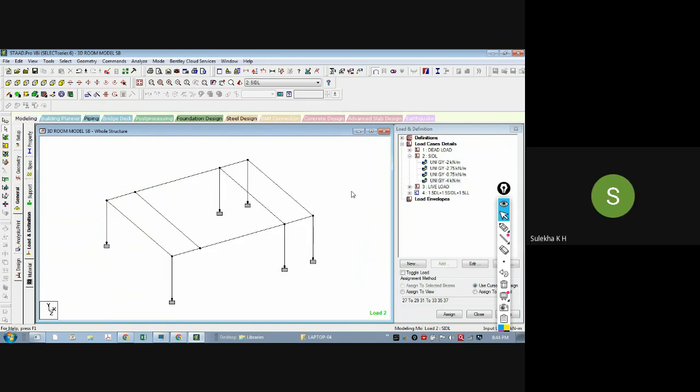So when we give floor loading, we can use the X range value also if we have many slabs at the same level. Yeah, but you need to give different X ranges, right? You can have the Y range same, but the X range will be different. Z range will be different, right?